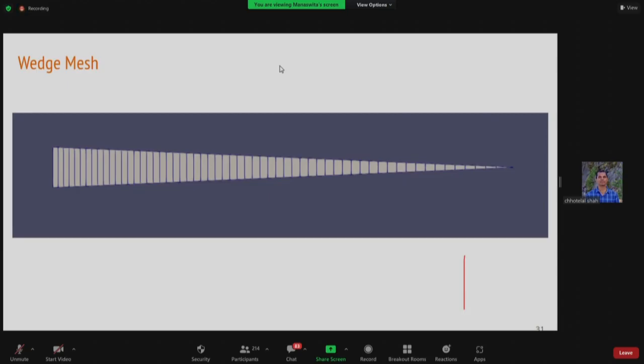Sometimes we use it like that, isn't it? Or if I'm wrong, please correct me. Okay, zero pressure gradient is something I need to check. Constant pressure, the pressure outlet condition, is the most general thing. You don't really have to assume anything.